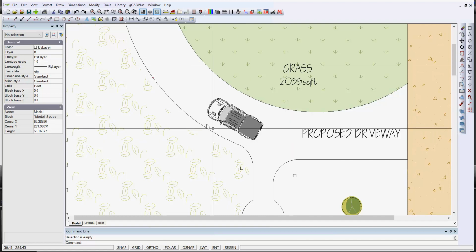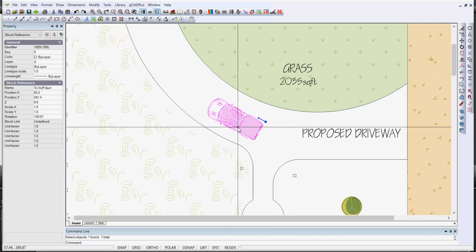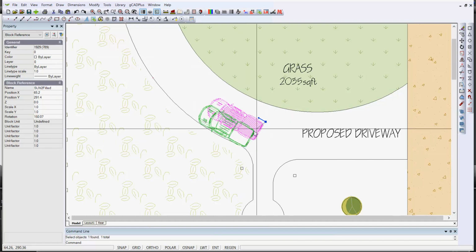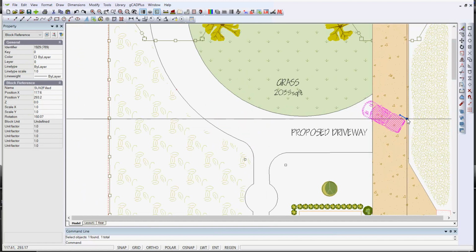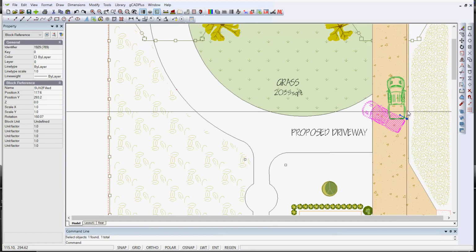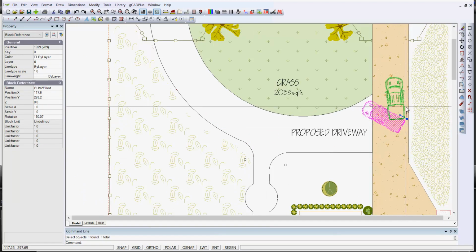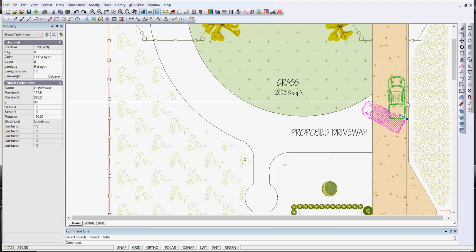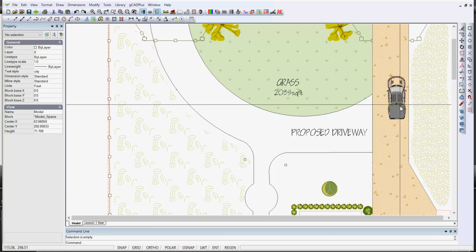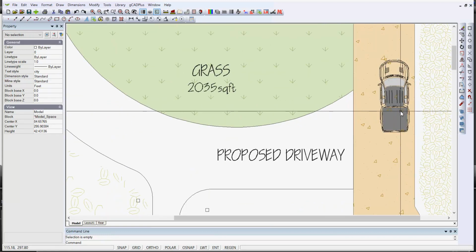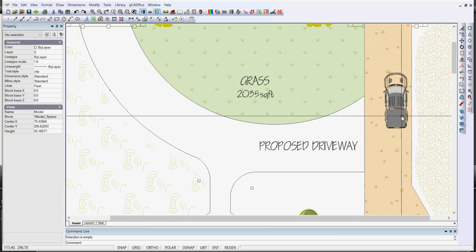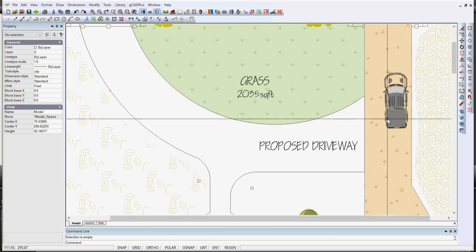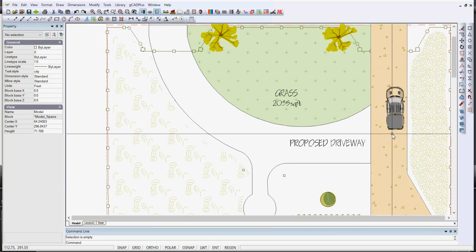So if I hatch through here, let me illustrate by just moving that one over there, and we'll rotate it, try and set it square on the driveway. Because it is hatched now, it's above the hatching. If we took one of the other symbols, you would see the hatching through it. So that filled symbol is quite a good one to use.